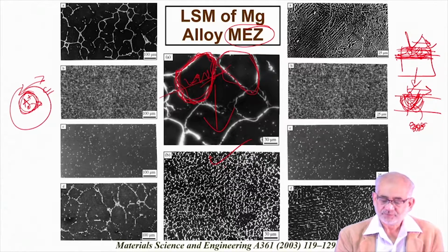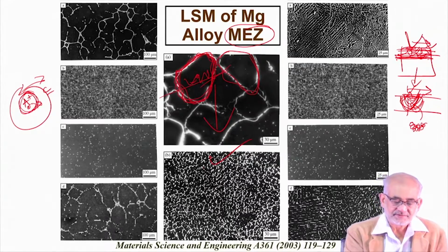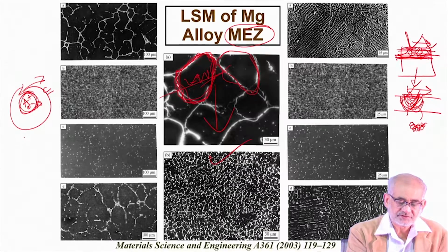One is improvement because of grain refinement and uniform distribution of these intermetallic phases, the hardness and the wear resistance improves. And on the other hand, another very important advantage is that from this microstructure, when you create very small crystallite size, where the distance between the core and the surface is so small that you cannot create a potential galvanic cell between an anodic and cathodic part.